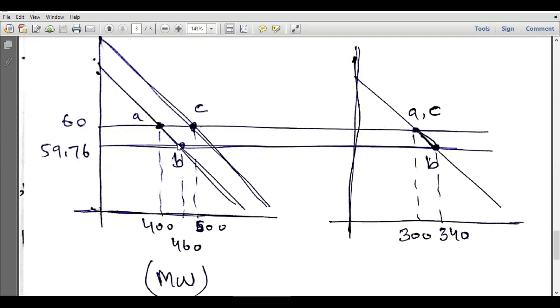So this first unit will increase its power further, such that all the load increment is contributed by the first unit. So that first generator will increase its power from 460 megawatts to 500 megawatts. So its operating point will move from this point up to this point. So its droop curve will also shift upwards, such that the system frequency is restored at 60 hertz, and the whole 100 megawatt excess power has been contributed by the first generator. So its output power will go from 400 megawatts to 500 megawatts. The droop curve will also shift.